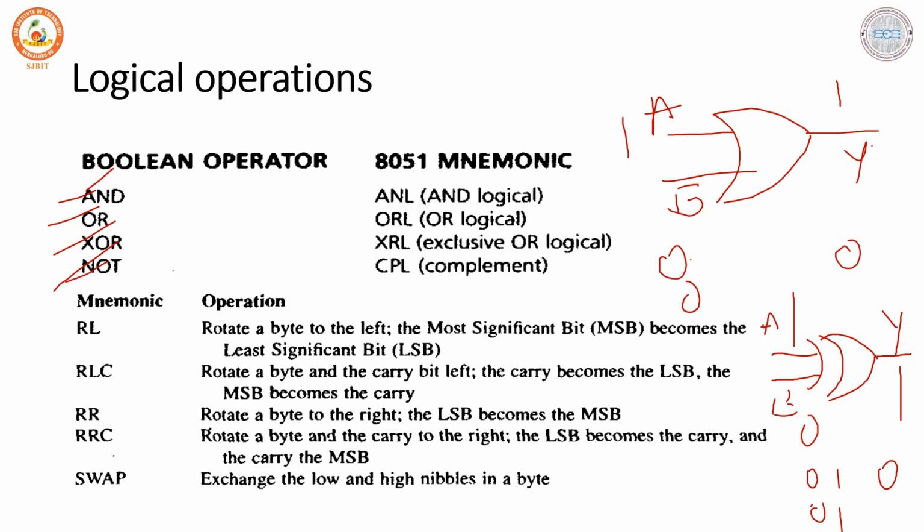And lastly we have the NOT gate operation, which is also called an inverter, which complements whatever input logic you apply to the gate. And the symbol representation of this is something like this. Whatever input you give, it will be complemented, A bar, and you call it NOT of A. And likewise we have some more gates like the NOR gate and NAND gate, and those are termed universal gates. We try to make use of those for performing all other operations.